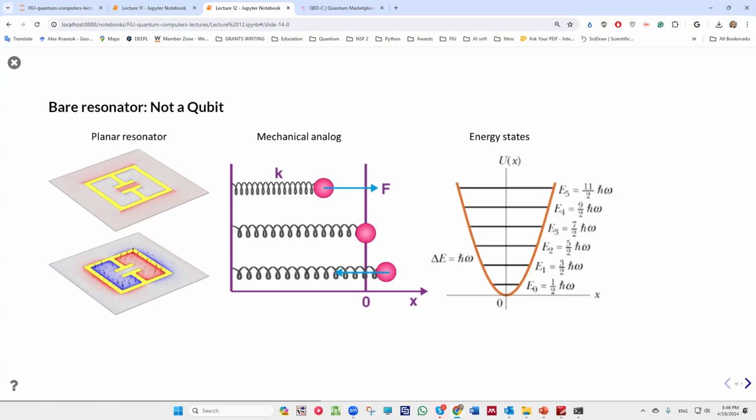But if talking about microwave, in microwave, we can first consider a resonator. So in this case, it's a planar resonator. Basically, what you see here is a slab, like a chip surface, with a gold microstrip in this shape, right? So essentially, this is a number of straight metallic strips with a central part with a gap. So this central part with the gap works as a capacitor.